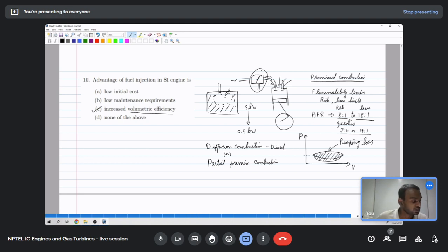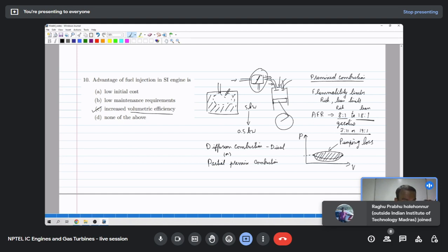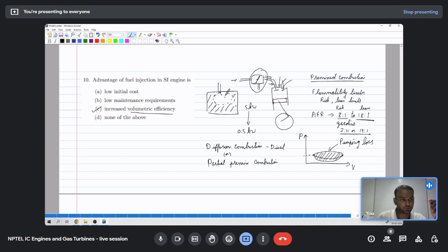Now say you have a very large capacity engine, say a 5 kilowatt engine, but currently you want to produce only 0.5 kilowatt of power. That means you have to put less fuel energy into the system, but just by reducing the fuel input you cannot achieve stable combustion. You have to decrease the air proportionally also.